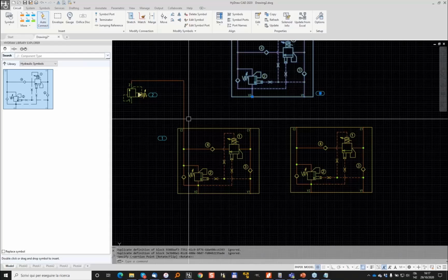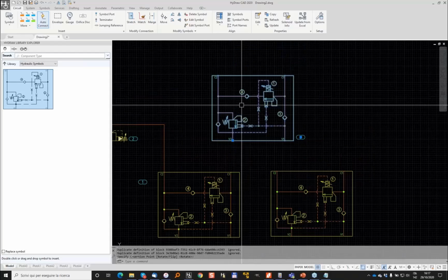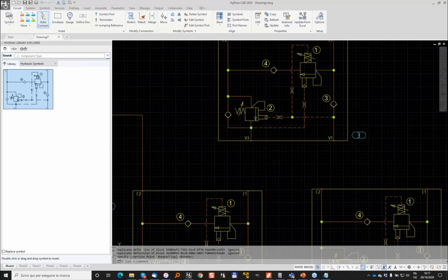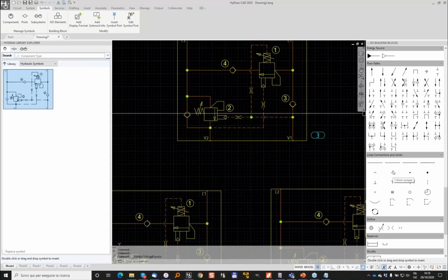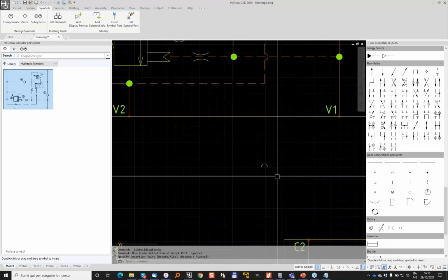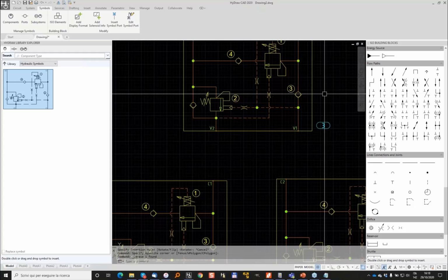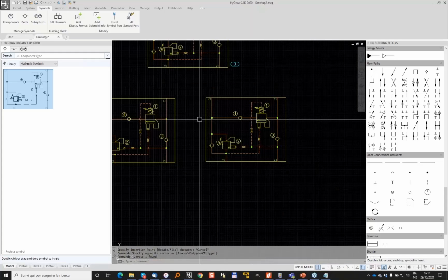You create jumpers, dots if needed, and please be aware that we have in the ISO elements, you find also the jumpers. So you can build really all the connection segments in pieces with lines and arcs. While on the other hand, if this becomes a diagram that you want to reuse, let me get rid of connection dots.